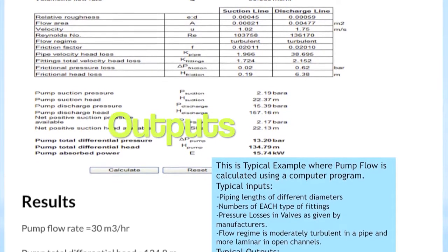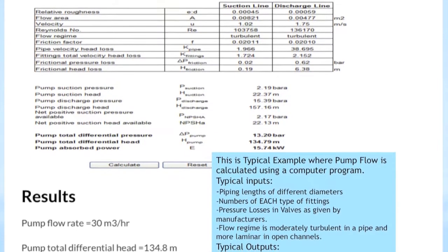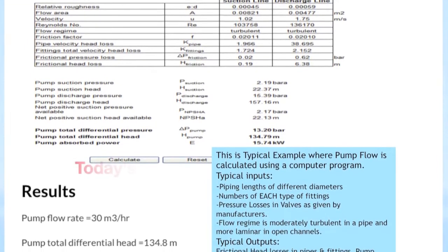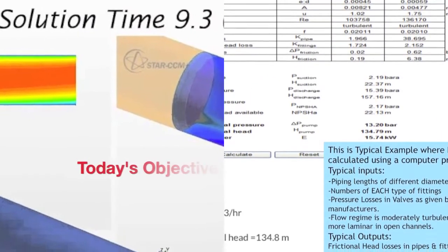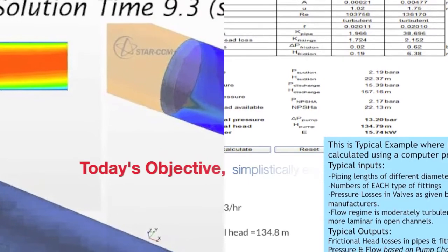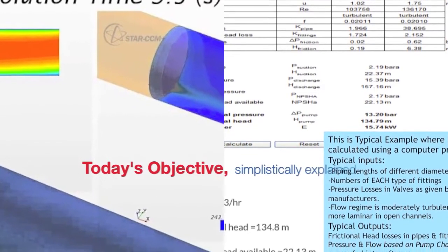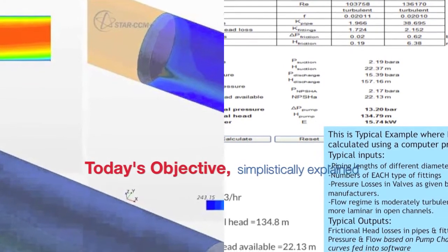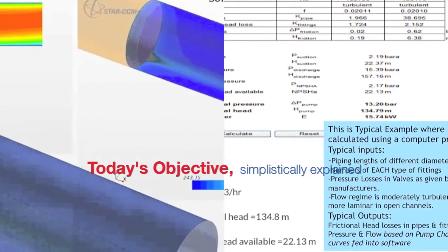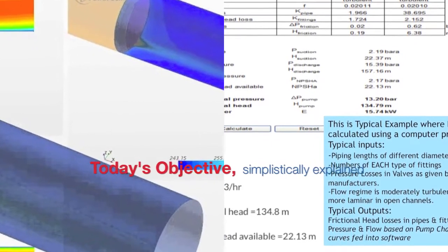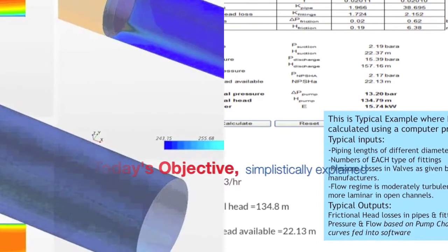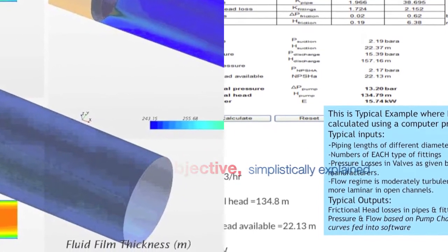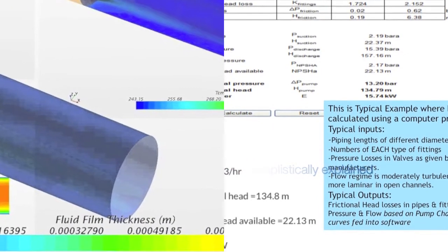We have got the flow through each and every exit point of the hydrants, and in the worst case, the frictional losses inside all of the pipes when all possible hydrant sprinklers are running. And in the worst case, we have got the flow, and we have calculated the total head loss when everything is working, and we have determined the maximum flow that is going to be given by the pump.